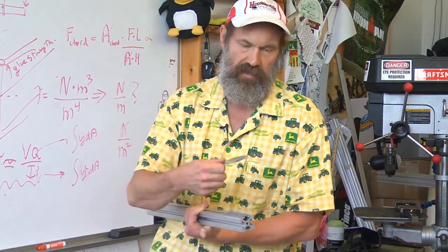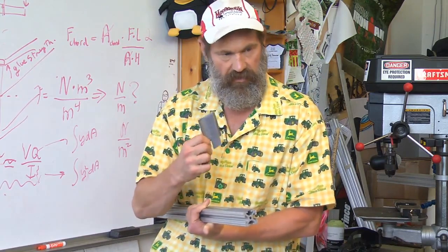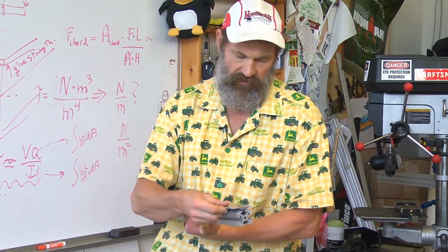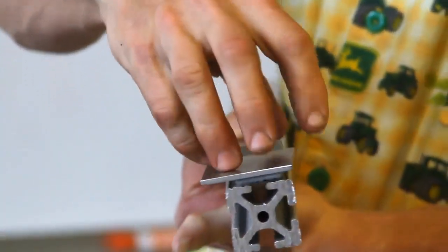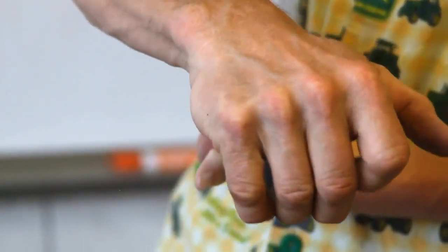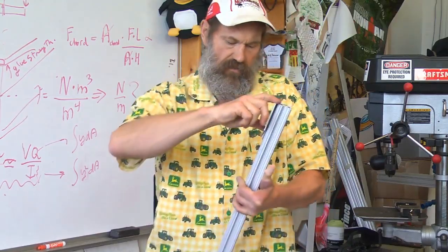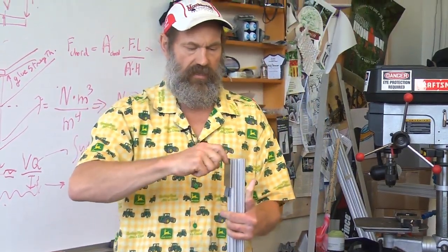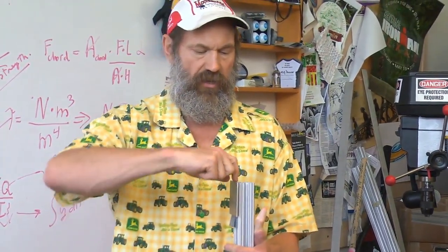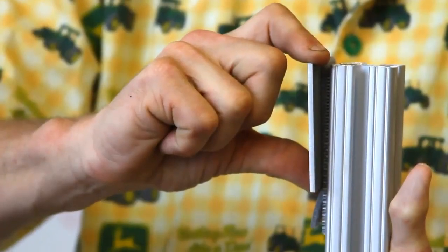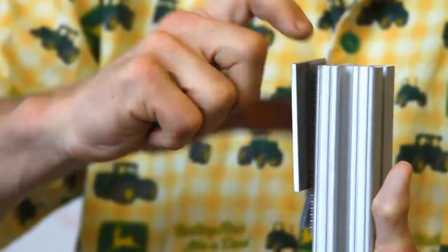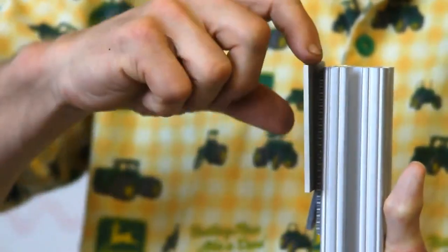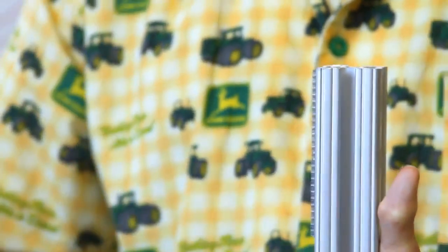In other words, the peel strength is much less than the shear strength for Velcro. And the reasoning is that when you're trying to shear it, you're acting upon the entire area at once. For peel, when you start to peel it, the compliance in this one structure allows you to start applying the stress at the very edge. And this is almost like a stress concentration issue. These guys are starting to let go up here. They're still attached down there. But as you pull more and more, you win.